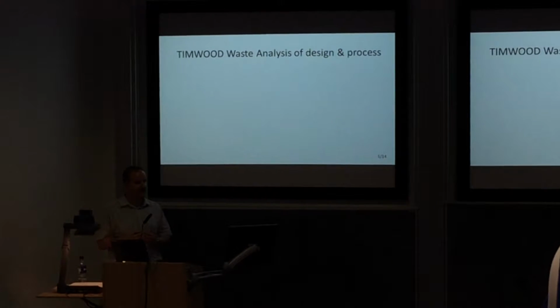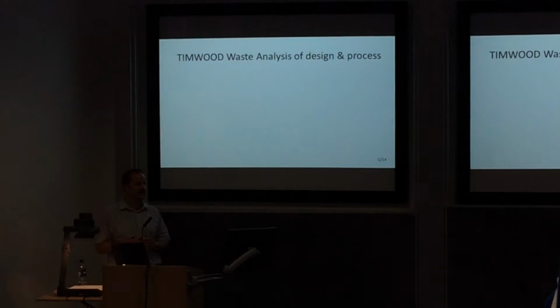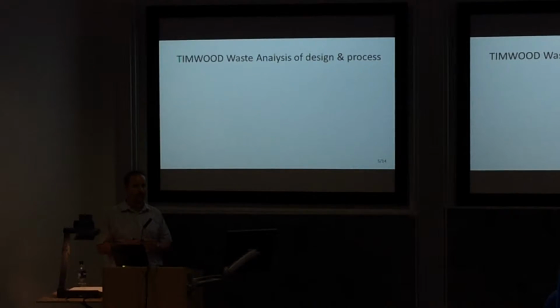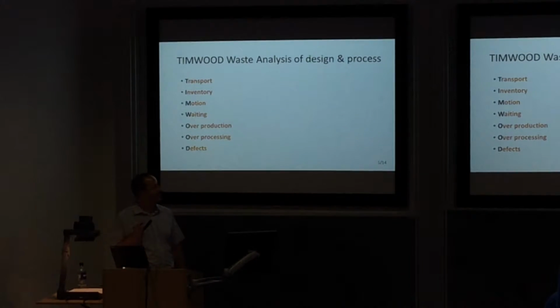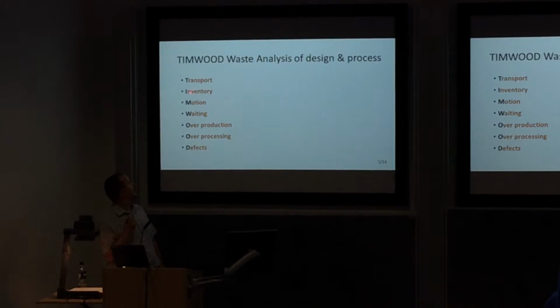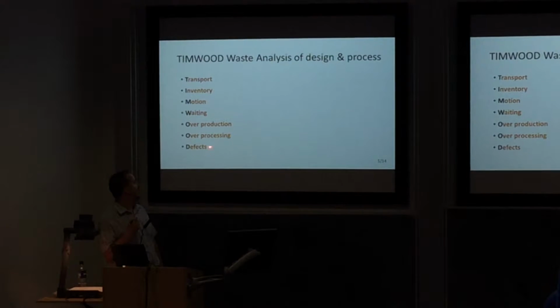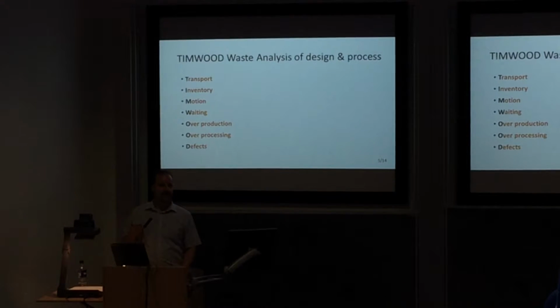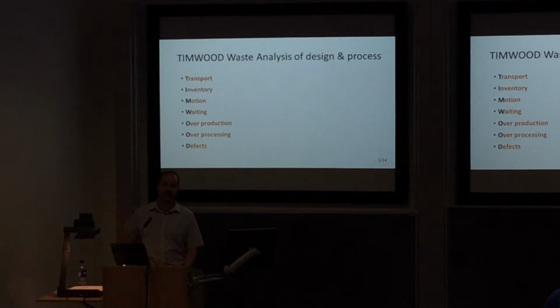Now, waste analysis is another part that I like to speak about. The easy way to think about waste analysis is an acronym called TIMWOOD. TIMWOOD stands for transport, inventory, motion, waiting, overproduction, overprocessing, and defects. This is also a very useful tool to use when you are looking at the process rather than the product. The process could be the design process, it could be the manufacturing process.